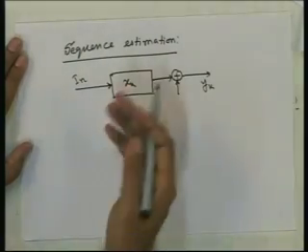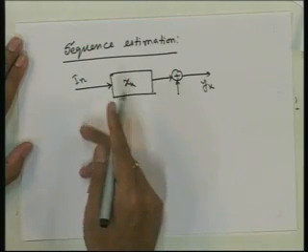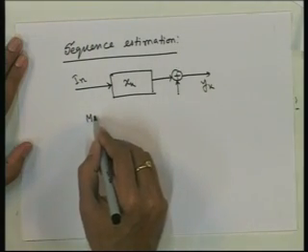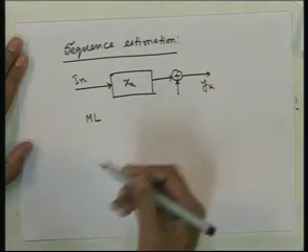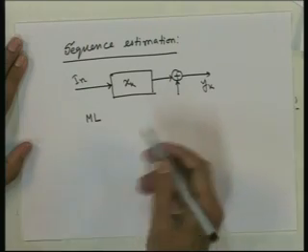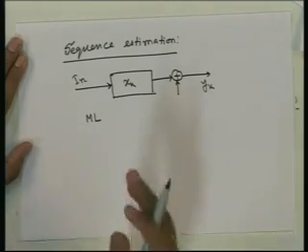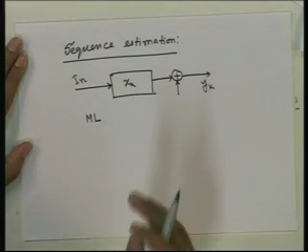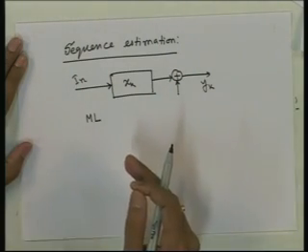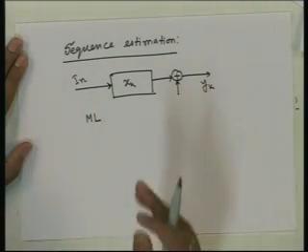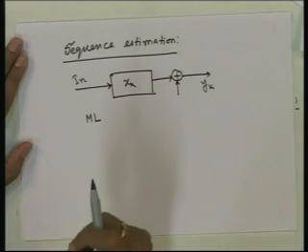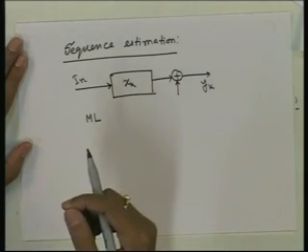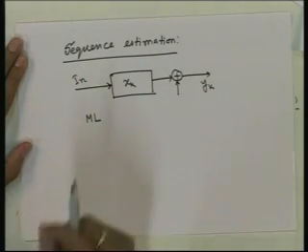And one can say one very useful criterion is ML estimation, which we have used for symbol by symbol detection for ISI free transmission. When there is no ISI, when we do symbol by symbol detection, we have used ML estimation. For the Gaussian noise case, we have seen that that is equivalent to picking up the constellation point which is nearest to the received signal.